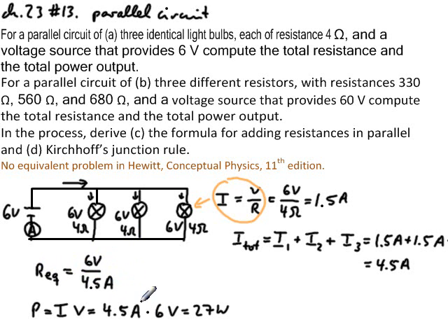And you'll be a little surprised because the total resistance comes out to 1.33 repeating ohms. So I'm just going to write down 1.33 ohms so we can see it at least, which is a little surprising because you look at 4, 4, and 4, and how could we possibly come up with 1.33 out of those 4s? Well, one of the things it says here, I haven't read this yet, is as the number of parallel branches is increased, the overall resistance of the circuit is decreased, and that's what we've seen.